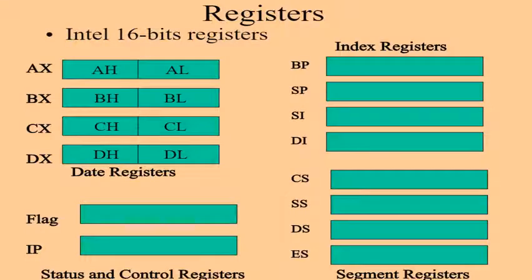The 80286 CPU family consists of all the basic sets of registers, instructions and addressing modes of 8086. The 80286 processor is upward compatible with 8086, 8088 and 80186 CPU. In this section, operations of the registers are explained elaborately. The 80286 base architecture has 15 registers.